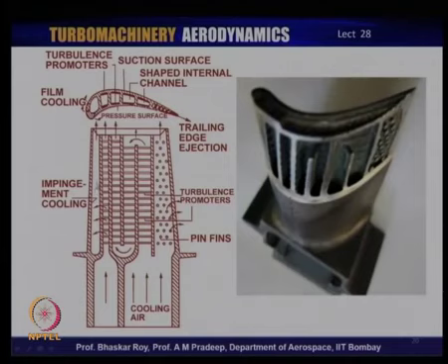As we have discussed, this impingement cooling is going on, and that air is finally also let out through the tip, and then a certain amount of air is let out through holes near the trailing edge to effect trailing edge cooling, which again could be a hot spot.